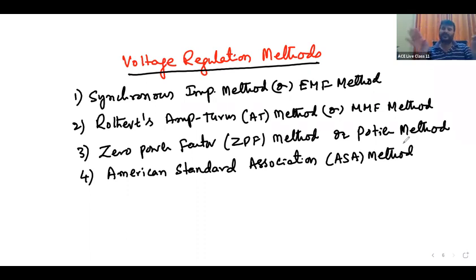So once the OCC and SCC characteristics have been drawn, you can leave the machine with that reading. You can calculate, all these are paperwork. Now you can calculate full load regulation, regulation at any power factor. All these are just calculations. Only indirect methods can be done. So these are the indirect methods to measure the voltage regulation.